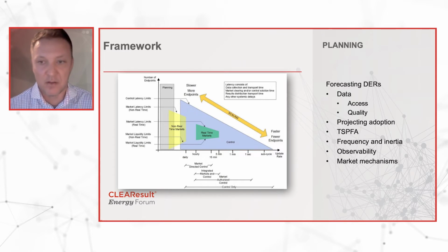So for example, if you have a microgrid with DERs on it and you've got blockchain pricing, you need to have at least as good as hourly interval data, although preferably something like 15 or even 5-minute interval data, the more discrete DERs points you'd have on that grid. So if you're dealing with thousands of potential points, then probably 5-minute interval data is appropriate for that type of application. And so the last piece of the framework is the grid architecture itself.